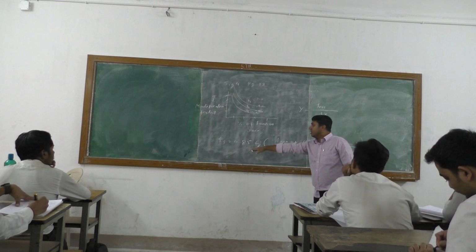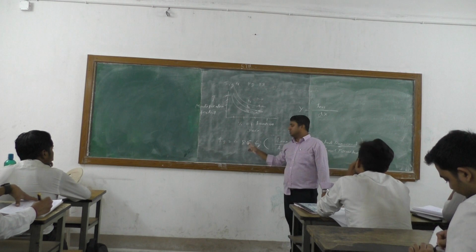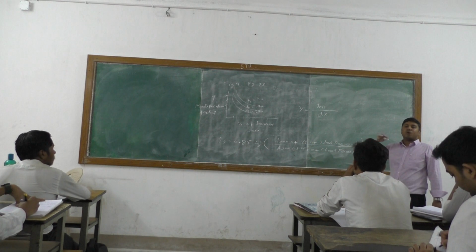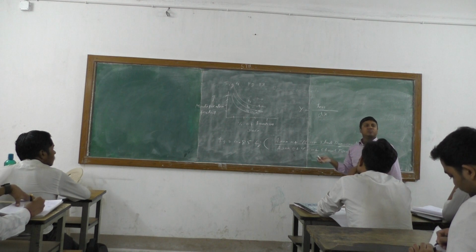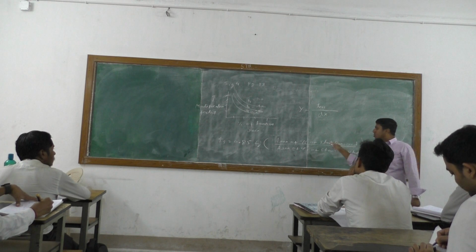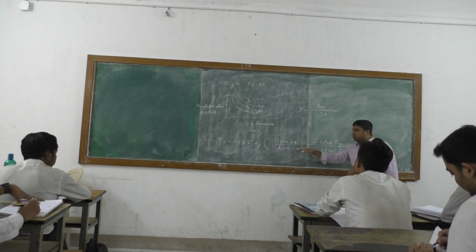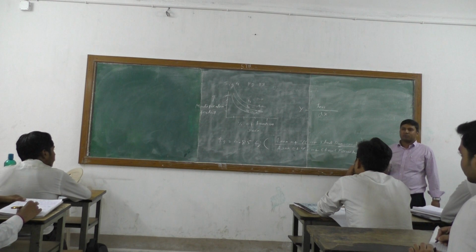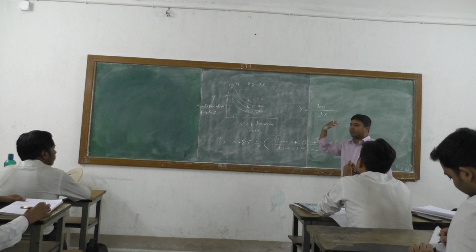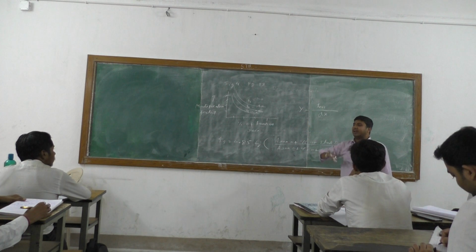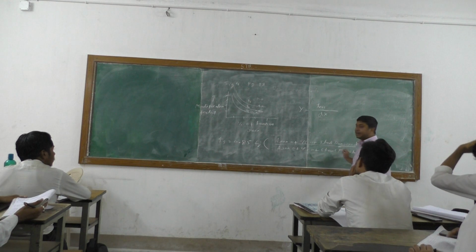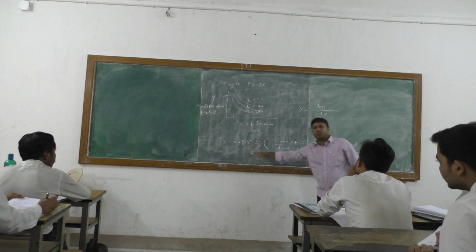So from this formula you know the value of Fy, 0.85 into the area of cross section of the steel required. From the previous problem that we have encountered, you can find out the area of steel that is required, Ast. Whatever steel is coming, we cannot get the exact value. Either we are providing sometimes more or less. So how much more or less we are providing, that factor, that modification factor, can be taken out by this formula.